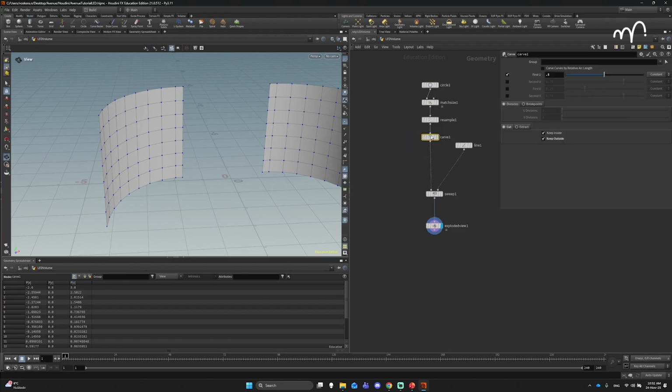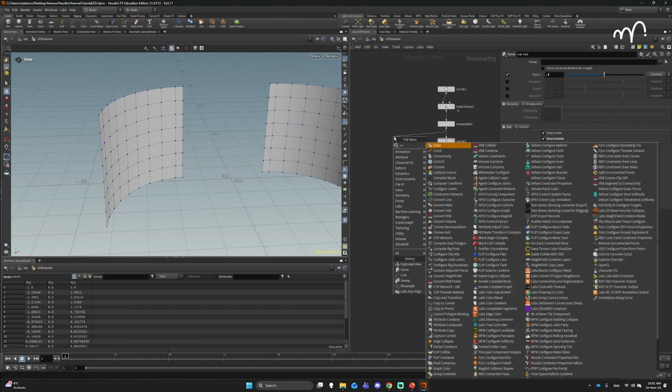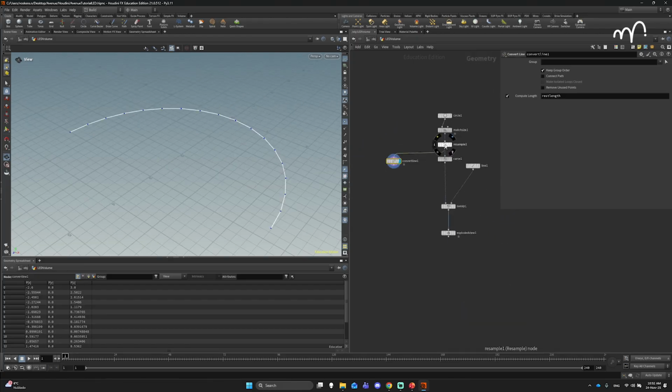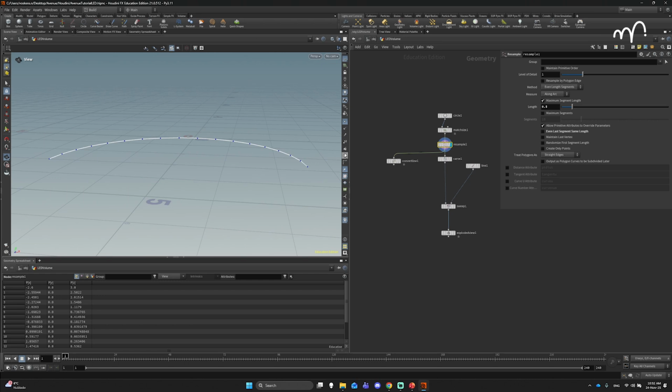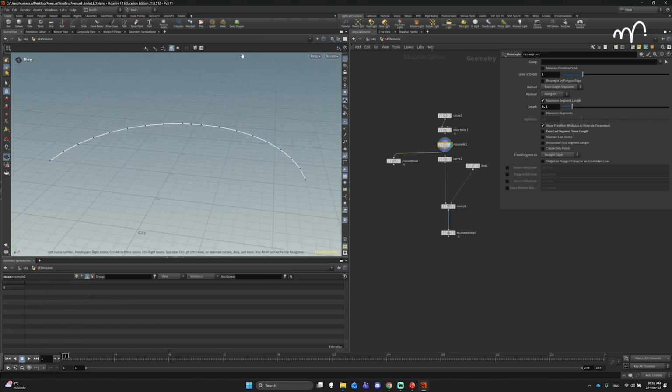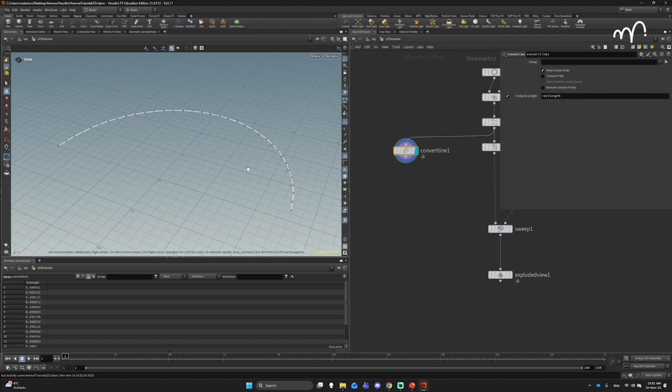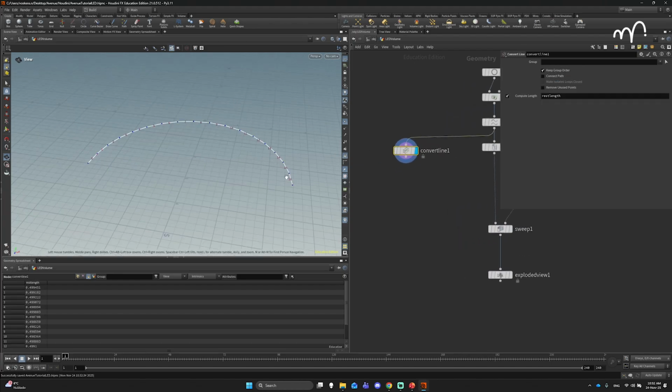We're going to add a simple line of wrangle, a primitive wrangle node, but first we're going to need to convert our line into split primitives. So what's happening with this node, you can see in the primitive number itself, points per primitive number. This is just one primitive. You can also see that here. One primitive doesn't have any data, but if I now do the example, or like convert to line, sorry, you get 0 to 16 primitives.